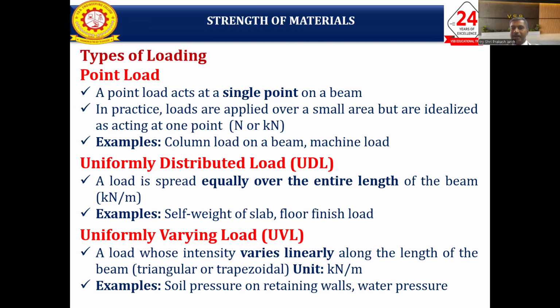Next, uniform distributed load. The load is spread equally over the entire length of the beam. Generally, the unit is kilonewton per meter. So per meter, how much load is carried, we can consider for the UDL. Example, the self-weight of a slab or floor finish, we can take as a uniform distributed load.